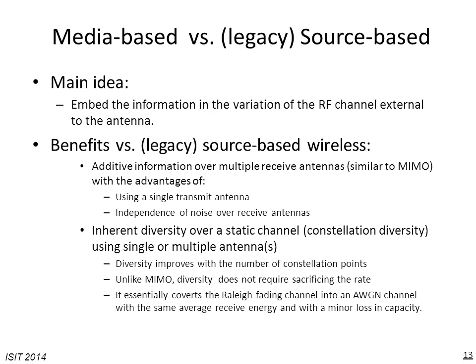The assumption is that the transmitter doesn't know the channel state, which channel states correspond to what configuration at the receiver, and blindly embeds the information by selecting those channel states, and the receiver knows what bit configuration corresponds to each of the received constellation points, where each constellation point corresponds to one of those channel states.